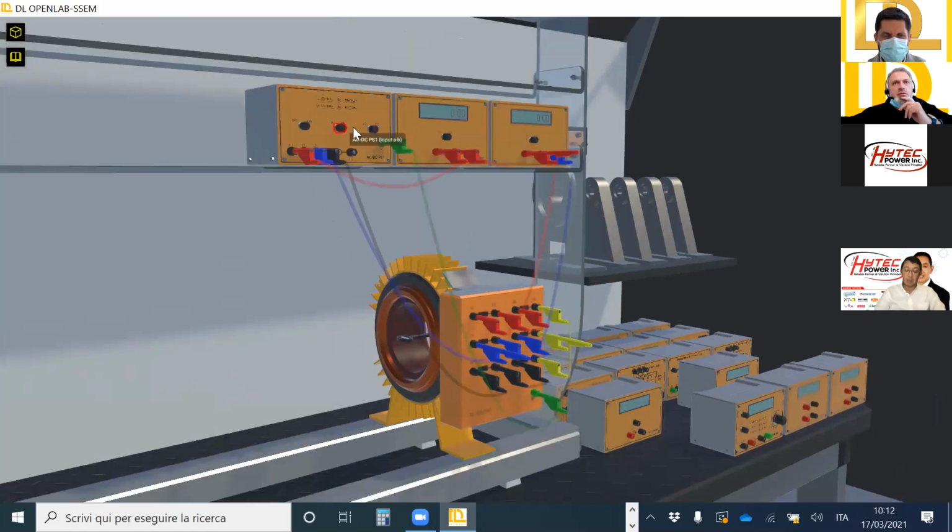We can see also, look, as I said before, now the selecting of A or B output or AC/DC is forbidden in this case. Also for this one, it's forbidden because we are in the measurement step. This one we can do because I need to turn on the power supply. So we have chosen a fixed 24 volts 3-phase AC. So automatically, when I put on this one, I will see on the voltmeter approximately 24-25 volts between phase and phase, and also the current in this case.